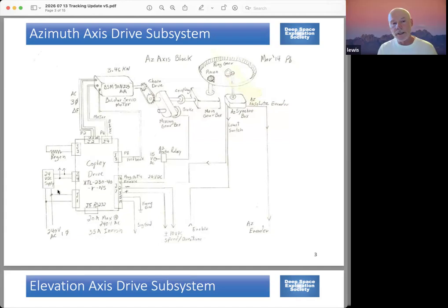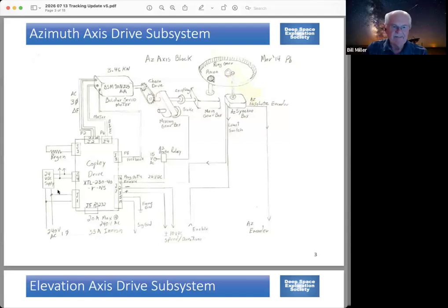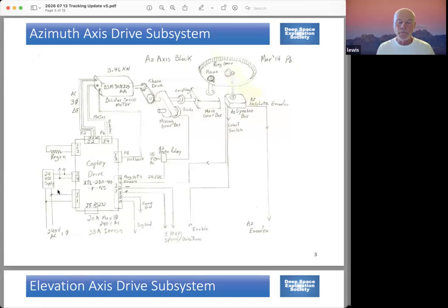It would also be good to have it as it is in the elevation with the VFD power switch. It'd be useful to have it in the ops building rather than having to go out to the tower to turn it off. But that's not a major thing. Yeah, if we could get a contactor similar to what we've got for the power in the hub, that would work out really well with a big stop button in the control room.